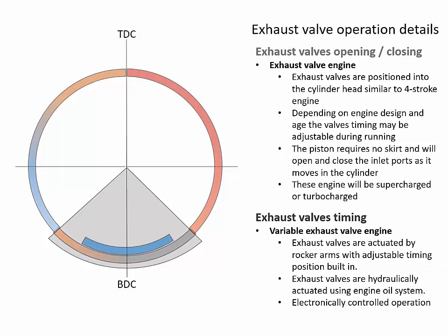So exhaust valves are positioned in the cylinder head, as mentioned before. The valves may be adjustable during running, either mechanically or hydraulically. The piston will require no skirt as there are no exhaust ports to keep closed. The engine will require supercharging or turbocharging.